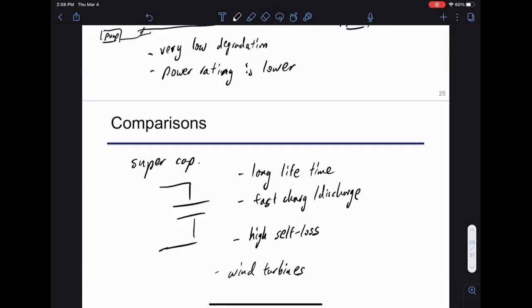This is technology you see in wind turbines. Sometimes instead of a resistor bank, you have a supercapacitor bank, and the hope is that if the fault clears fast enough, this energy can be routed to the grid again. So these are all possibilities among the different technologies.